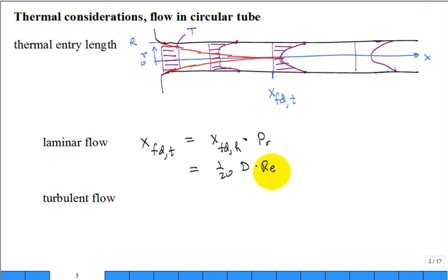And we took a look. We plugged in that equation, put a Reynolds number of 200, put a Reynolds number of 2,000, and you'll see that usually it varies between 10 and a little less than 100 diameters. It's pretty hard to have that long. And now you multiply by the Prandtl number, and that's the change for the fully developed thermally.